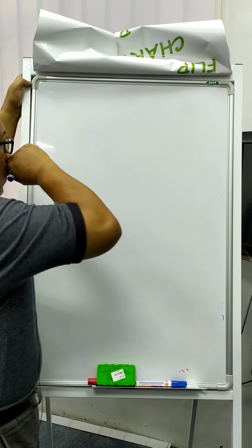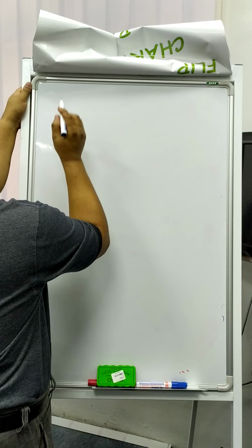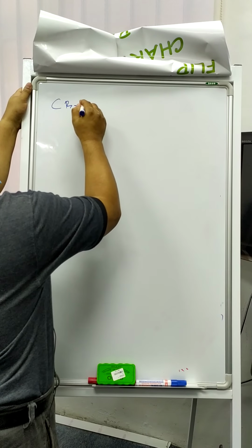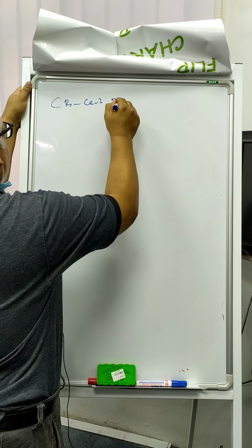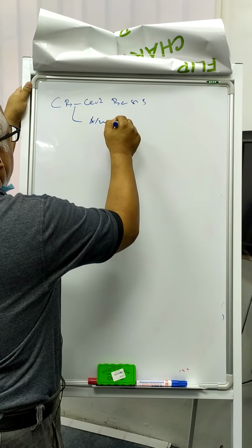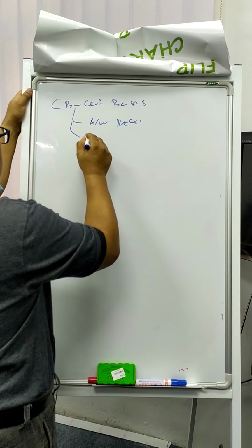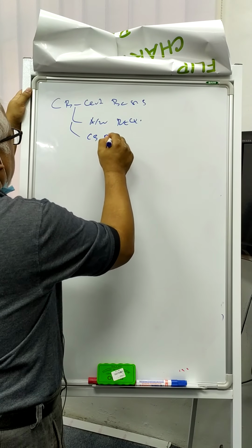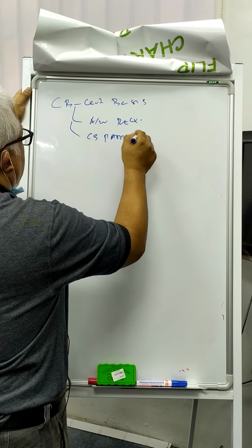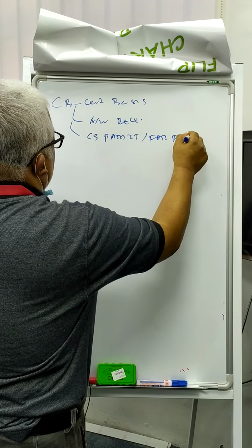What you need to understand is that every aircraft is designed to a certification basis. In the cert basis, there is airworthiness requirement. For large transport aircraft, we talk about CS Part 25 or FAR Part 25.